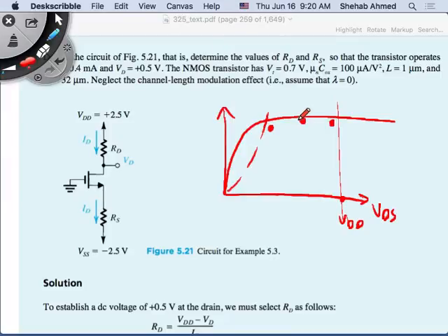Probably somewhere in the middle, because if you're close to here and you put in a small signal that you want to amplify, you're amplifying VDS. If you amplify it and it passes VDD, that's not good, because we know from op-amps and physical circuits that you cannot get an output from an amplifier greater than your power supply voltage.